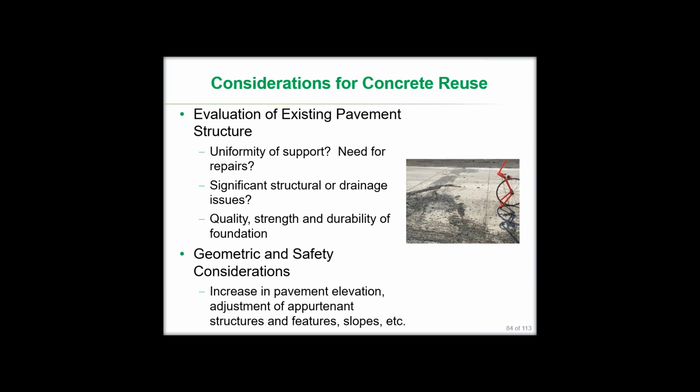Other evaluation conditions would include issues concerning the structural integrity of the pavement or drainage issues. You may have a pavement which in itself is inherently in fine condition, but if there are known drainage problems that are going to limit the life of the overlay or the rebuilt pavement in that area, then that may be a question as to whether or not you need to actually go in and address those issues, which may prohibit you from actually reusing the pavement in place. It may become a recycling project in those cases.